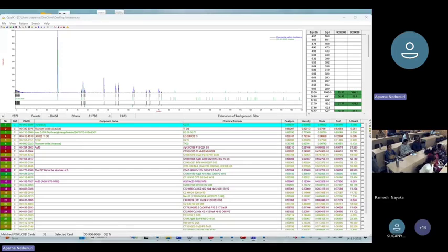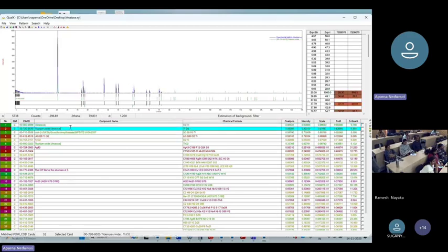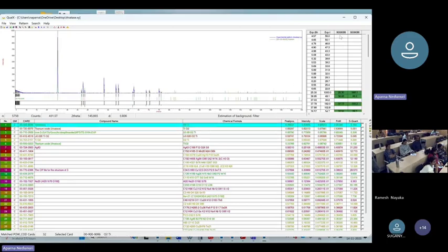If you click on this, in this corner over here, this is your experimental 2 theta and experimental intensity. This is the data of your sample. Now we are trying to match the peak intensity and peak position from the CIF file of each phase. If I click annotates, it has this card number you can verify. Now it is saying that at 25.3, we also have a peak at 25.3 in our sample.